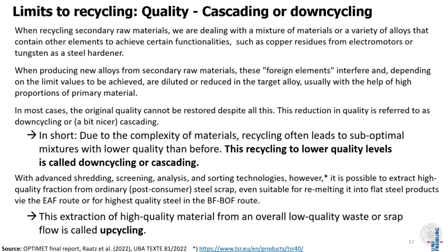And the reason simply is that these products don't need to be rolled out to very thin sheet metal. The thinner you get, the easier it is that things get brittle, or you get cracks, or the stability isn't high enough. For long products, that's not such a big problem. First of all, they're not very thin, so you don't have the cracking problem. And second, in case the quality is a bit lower, you can simply make them a bit thicker and it will be fine.